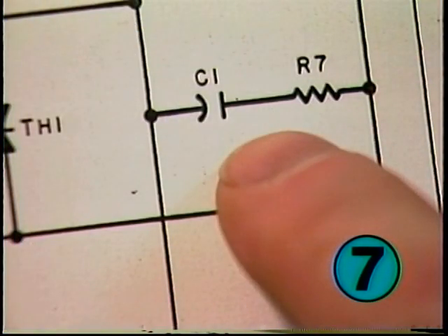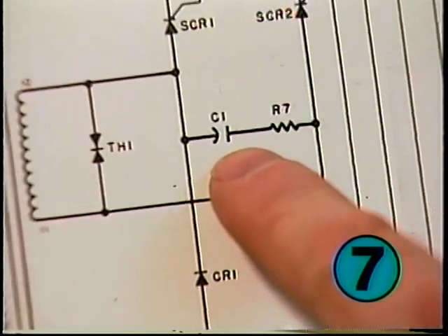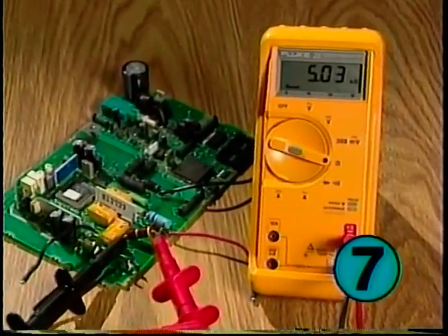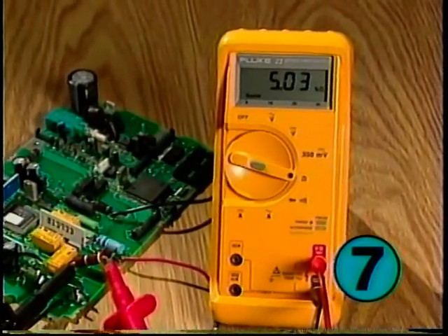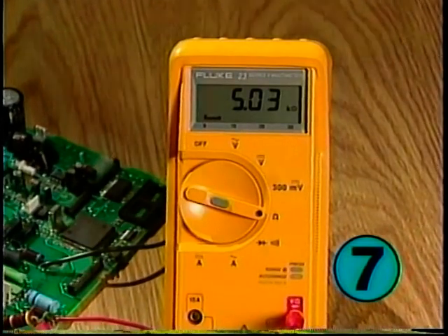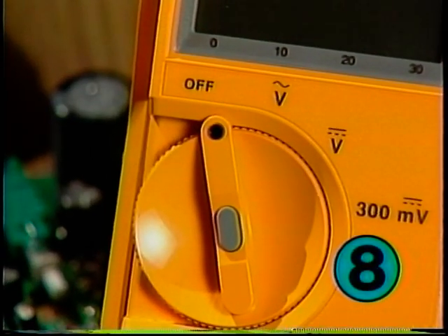Check the circuit schematic for parallel paths. Parallel paths with the resistance under test cause reading errors. Do not touch exposed metal parts of the test leads during the test. Resistance of your body can cause reading errors. 8. Turn the meter off after measurements are taken to save battery life.